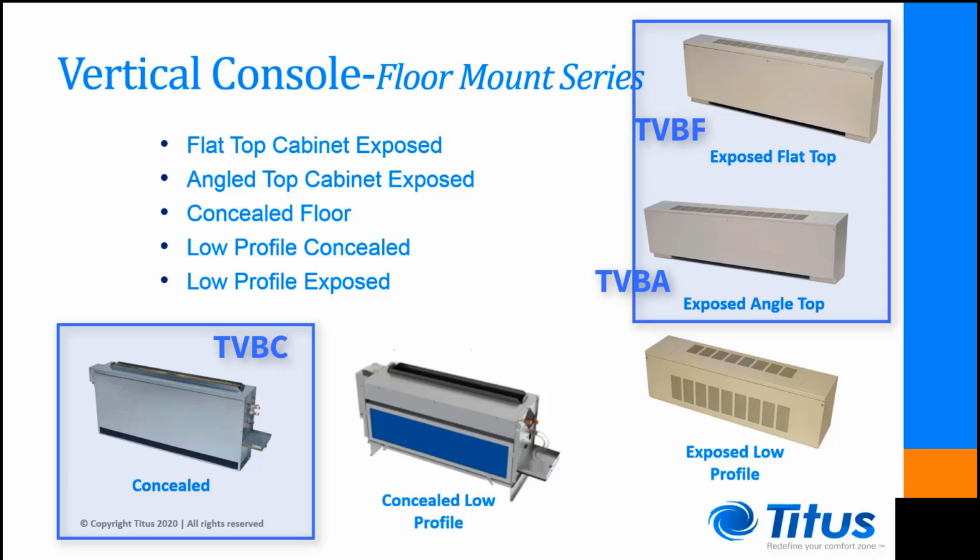The last full-size unit is the TVBC in the bottom left corner of the screen. Right away we can see it is not painted and therefore not meant to be seen by persons in the occupied space like the TVBF and the TVBA are. It is meant to be installed either behind a wall or in a project site provided console cabinet that would fit around the unit. If this unit is behind a wall, then it must be ducted to the living space to be conditioned. If installed in a console cabinet, then it would discharge through the supply opening in the top of the cabinet. We will see later on an example of a project provided console cabinet around the TVBC.